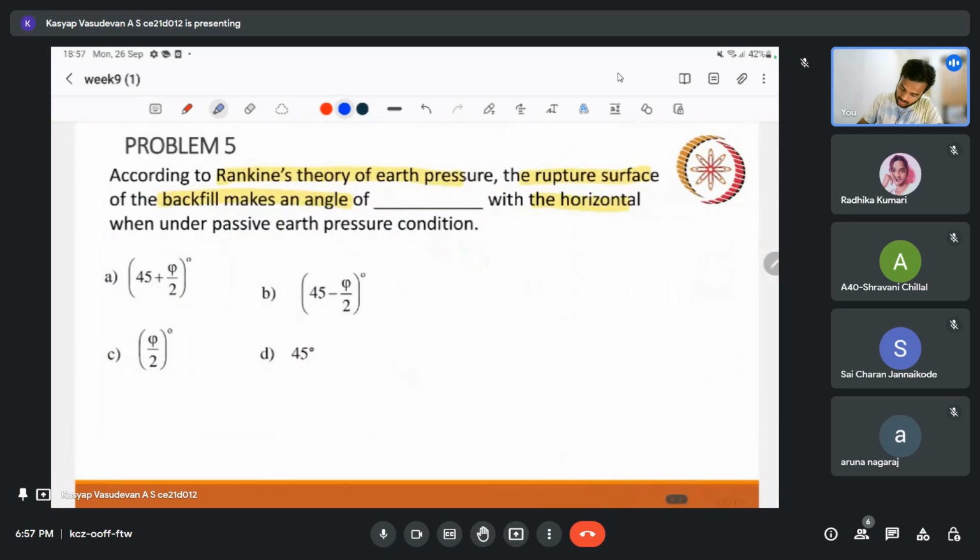In this plastic case of both active and passive, let us say a soil is failing with respect to active and passive. It is said that it will have different slip lines. So let us say this is active. This is a trick to remember this. So I'm trying to show a trick to remember what it is. Let us say this soil is failing on the left side in the active case, and the right side is in the passive case. For whatever reason, let it be bearing capacity, either footing or whatever load is acting on it, let us say that it is failing.